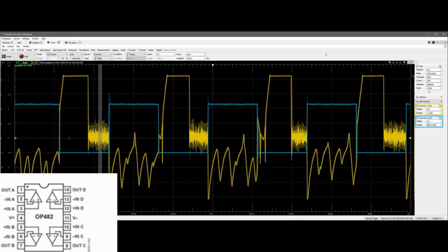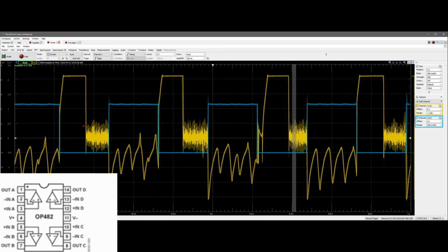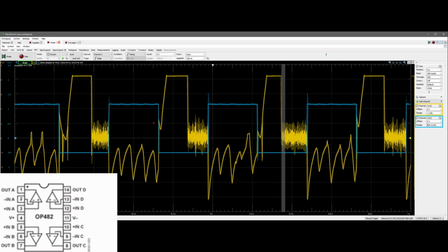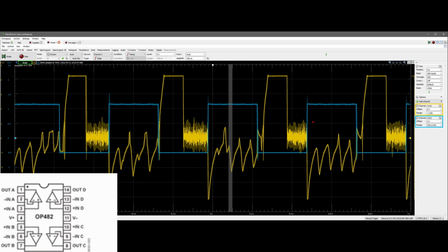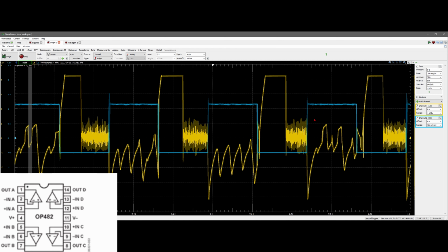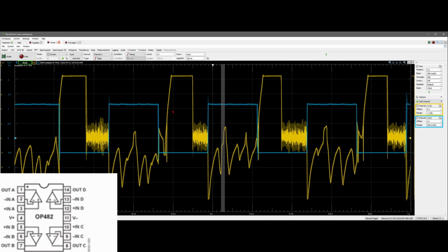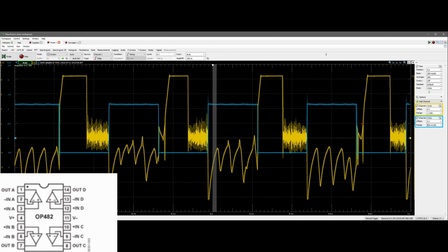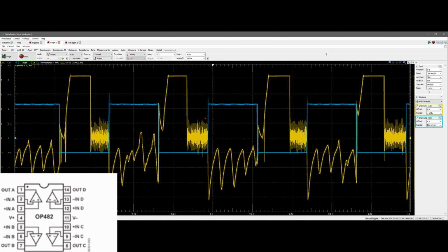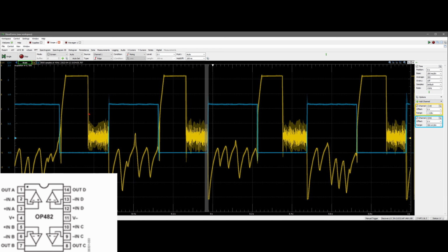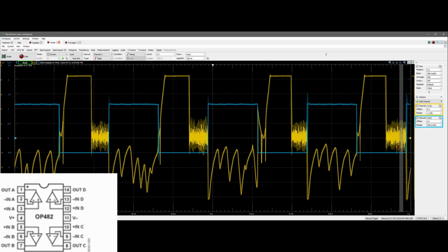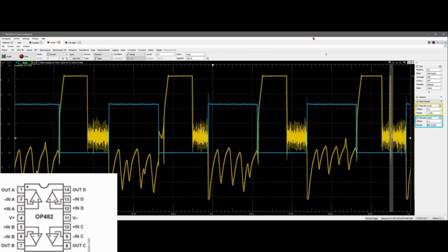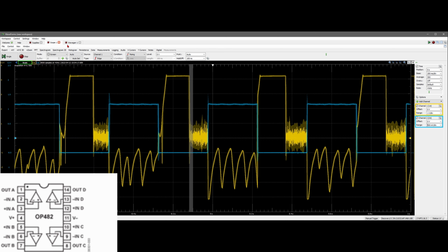Now, it is not perfect. We can see that for sure. If I put my finger over the infrared LED and the phototransistor, I'll do it in a second. But this is what it looks like without my finger on it. And if I were to put my finger on it, it would just look something like this. So not too much is changing. We can see that stuff is moving, but I'm not sure if it's just from my finger. So I've taken my finger off of it, and it looks like it is still changing without my finger. So it's not too big of a deal right now. We do have a lot of noise though. Hopefully we can clean this up though when we look at the next part of our circuit.